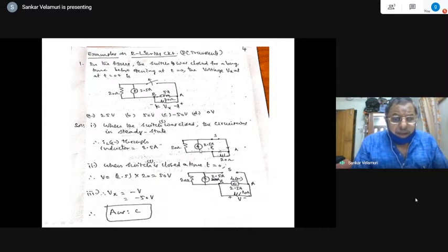So now the current flowing through this one is how much? So this is AB and this is the switch, and short circuit takes place through the inductance. So this 20 ohms becomes ineffective. So current flows through this, current source is here. This 20 ohms also gets shorted because it is directly connected across this one now. So the current flowing through this, IL0 minus, through the inductor is only 2.5 amps.